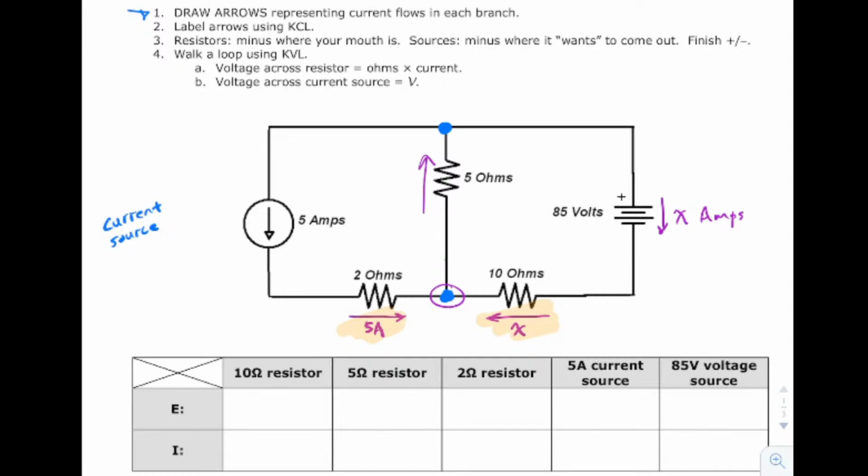Okay. Now I'm saying guess because I don't know for sure that over here this is actually flowing down. How do I know? I suspect it could be, but for all I know, it goes this way. We don't know. But don't let that worry you. Just draw the current in a way that seems to make sense. Do your math. And if you happen to get a negative answer, that tells you, whoops, you drew it backwards. That's no big deal. Just the negative is part of your answer. And again, it indicates that you drew it backwards.